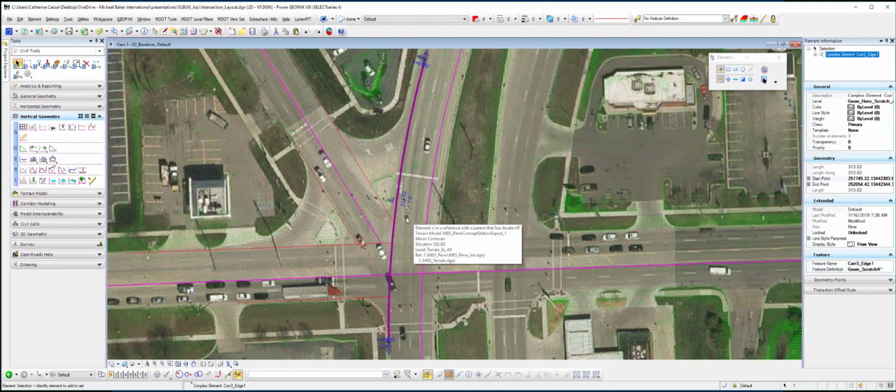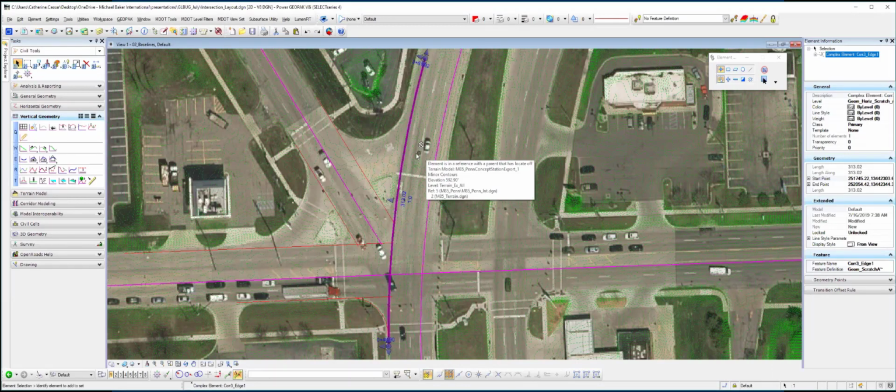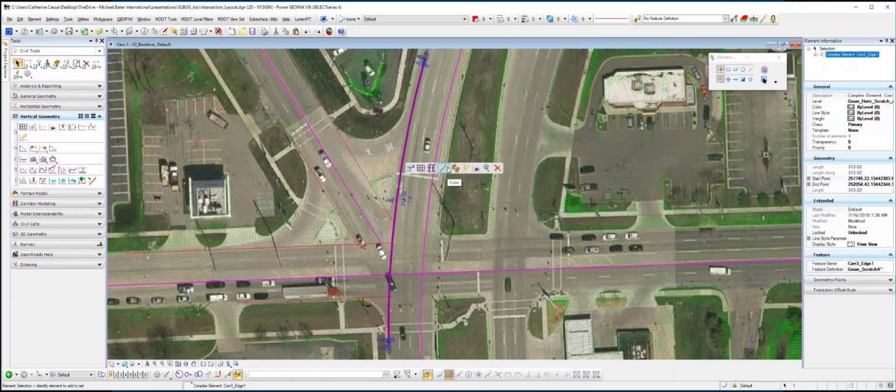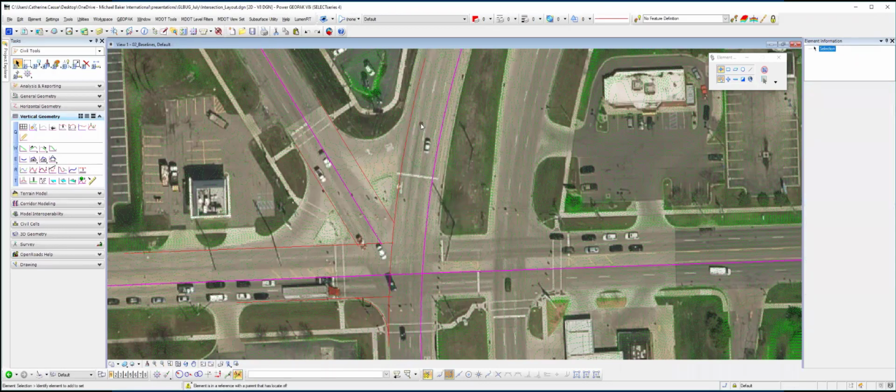And the reason is, because this is the seam of two modeled surfaces, from the roadway to this complex intersection model, you want to make sure that this ties in exactly and that the seams are solid, so you don't have any type of a bump or gap or break between the two. So in this case, I'm not coming from the alignment for its horizontal position. I'm building it right off of the model itself. The only caveat to that is, should something happen to this corridor, this could cause my surface model to have a problem. And then you've got to do basically a reattach on the rules and try and see if you can get it to work.